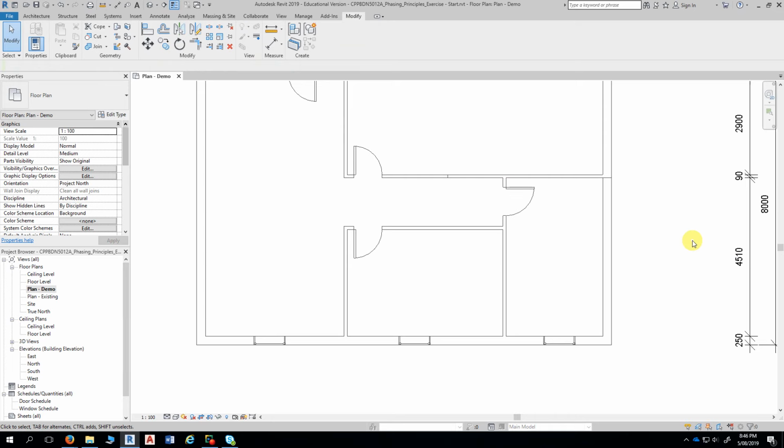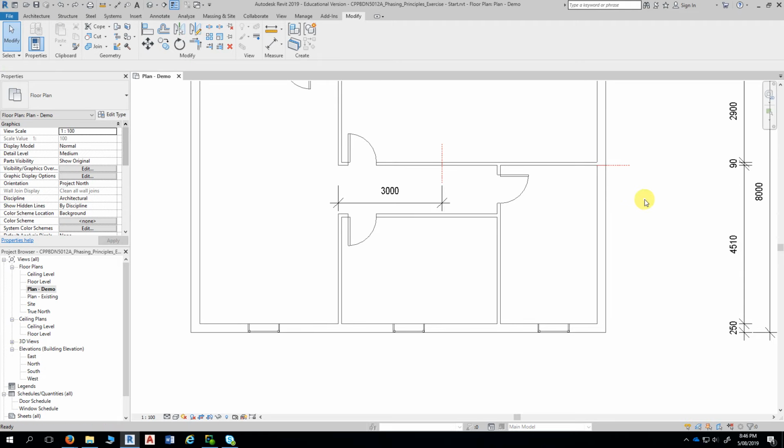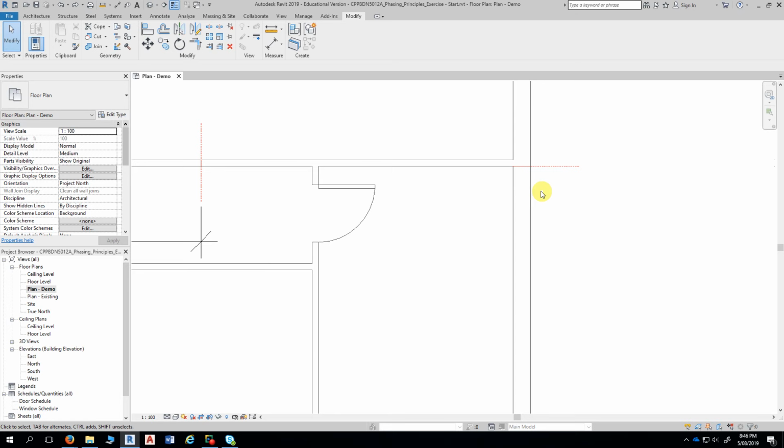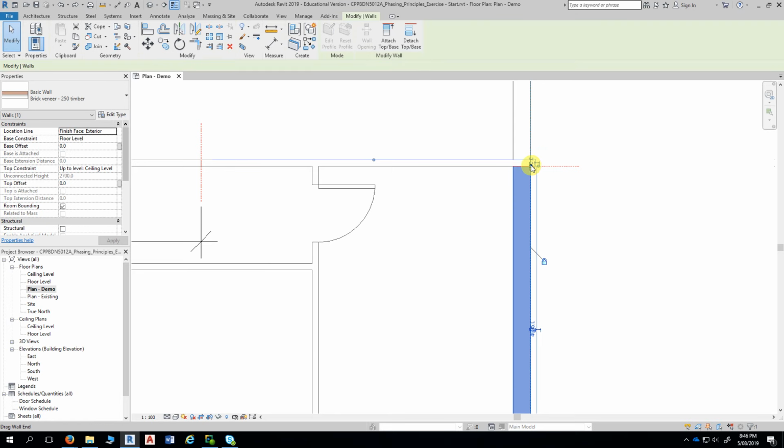My second wall is crossing the reference line. It's going up above the reference line. Yeah, you would have got a warning that you have overlapping. Yeah, I got the warning, but I have overlapping. Yeah, that means that you actually took this one. I'll just bring that reference plane back again. So you would have taken this one up first and then this one second. Yeah. So the order is important. Otherwise, you'll get an overlap and you'll get a warning.